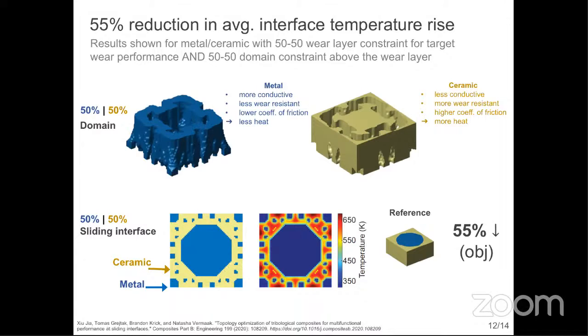These end up forming connected root-like conduction paths through the height of the structure at the four corners to the top surface heatsink. And these metallic interfacial inclusions also increase the contact area between the two materials, which enhances the heat conduction from the ceramic to the metal.